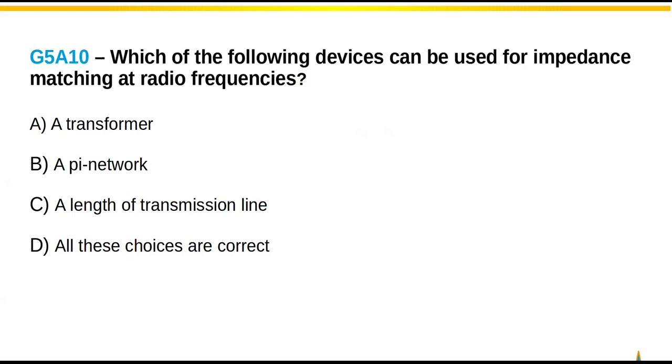Okay. All I was saying is that the total current from the 13.8 is not the final amplifier. But if you look at the difference between transmitting and not transmitting, that delta current times the voltage is going to be a lot more than 100 watts. Of course. Okay.